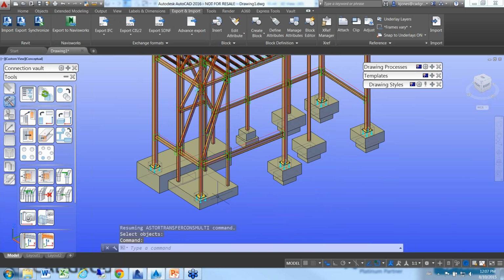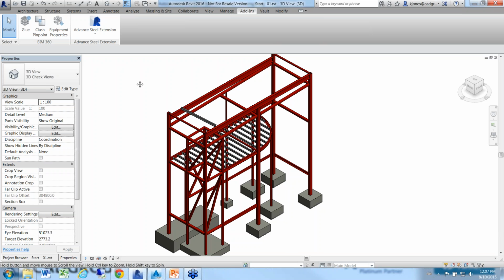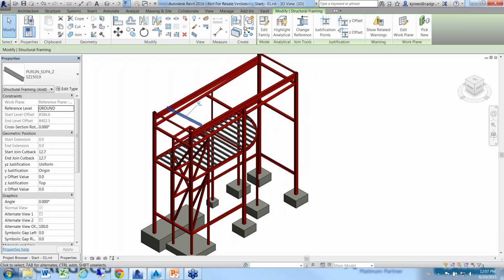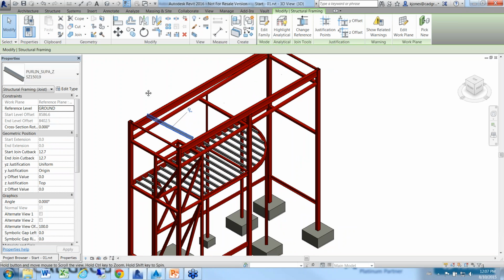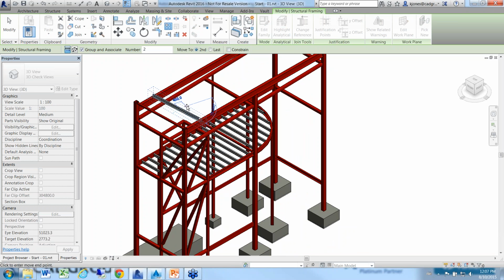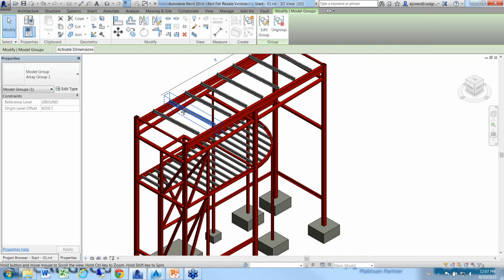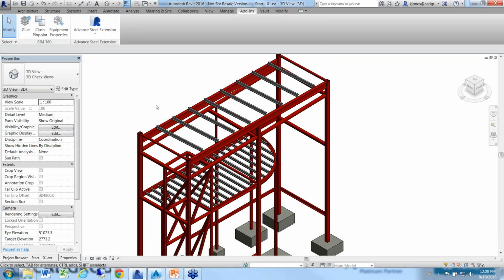Now, more importantly, what can happen as well is that the Revit model might still be in its fundamentals at this particular stage. So there might be further work that's done from the architectural, the engineering side of things on the actual structural model. In this case here, I'm just going to quickly do an array and add some more purlins in there at this stage. So using some of the basic Revit functionality, guys. Not my area of expertise, but not too hard to quickly work out. So I'll drop in 8 of those guys. Okay, and we're happy with that so far.